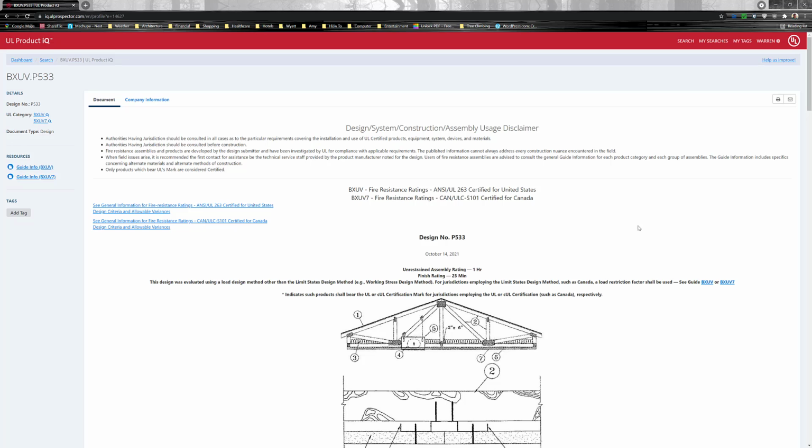Manufacturers pay a lot of money to have their products tested in these things, and sometimes you'll have little gotcha moments. We can give a good example. Let's say the Huber Zip System. The Huber Zip System has a sandwich panel where they have a quarter inch or a half inch of sheathing or whatever it is, and then a half inch of foam insulation. Well, that product has a flame spread on their foam that doesn't really let it be used with certain UL assemblies. They had to come up with their own special UL assembly to get that product to meet Underwriters Laboratories